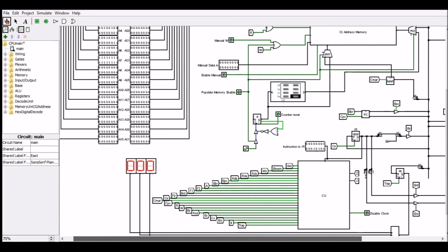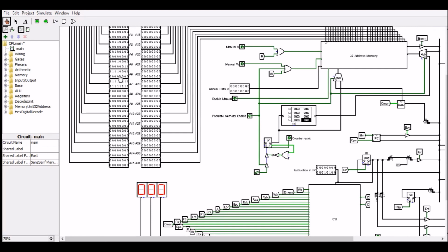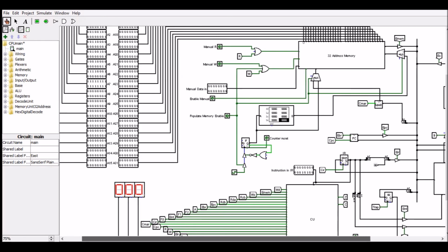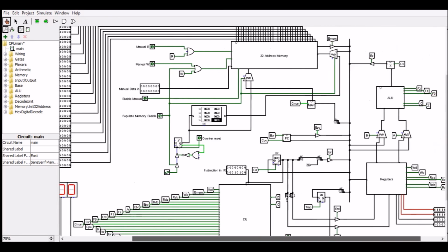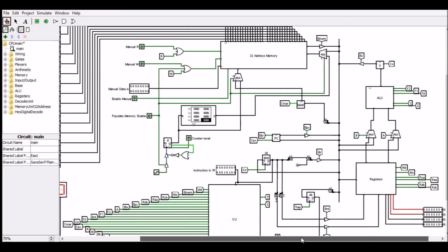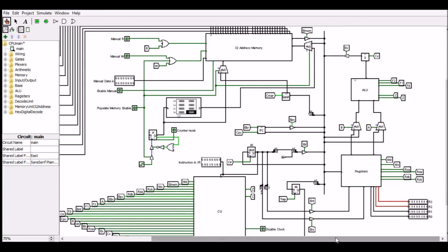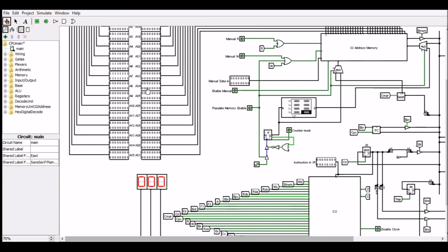And then once we have that, we're using the branch if not equal instruction, which means we have to look at the 0 flag, and if the operation has enabled the 0 flag, if R0 contains 0, then the condition would not be met, and we would continue here where we would trap the result being output because we would have finished the program.